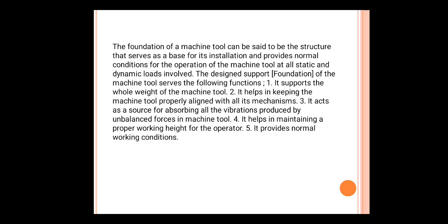Second, it helps in keeping the machine tool properly aligned with all its mechanisms. Third, it acts as a source for absorbing all the vibrations produced by unbalanced forces in machine tools. Fourth, it helps in maintaining a proper working height for the operators. Fifth, it provides normal working conditions.